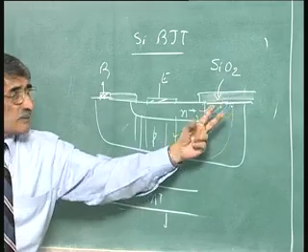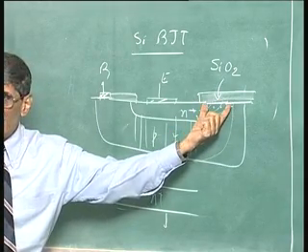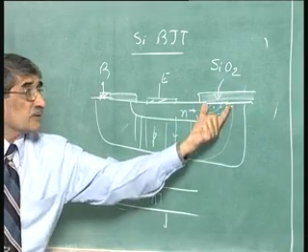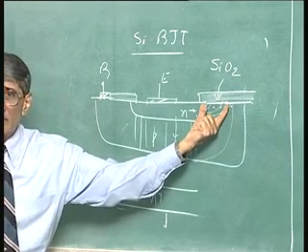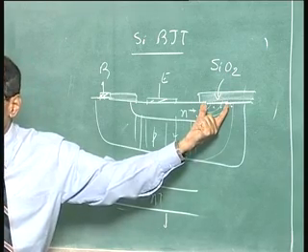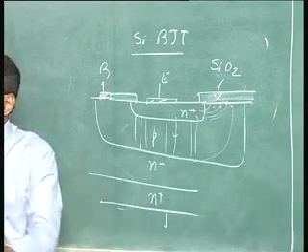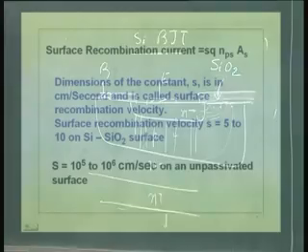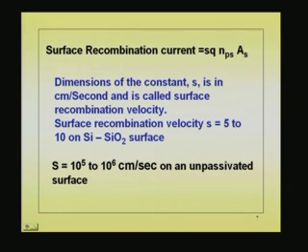Okay. So, you have to take this area into consideration, and the current reaching the surface is due to the recombination there, which actually is the recombination current which gives rise to base current. So, that is what we have put here. The carrier concentration on the surface decays from the emitter edge away to 0, Np0 to 0, into the area. So, the product of these two gives 1 by centimeter cube into centimeter square. This gives 1 by centimeter.